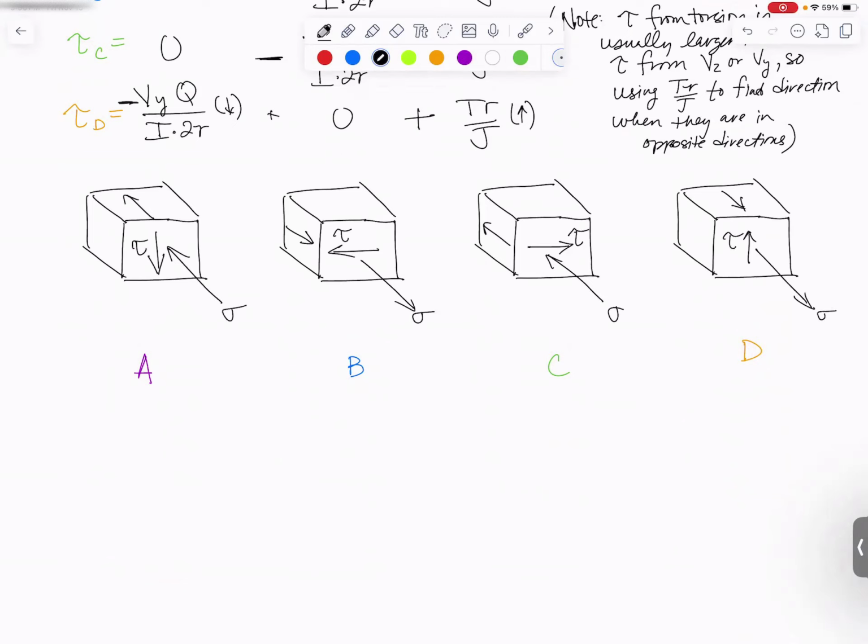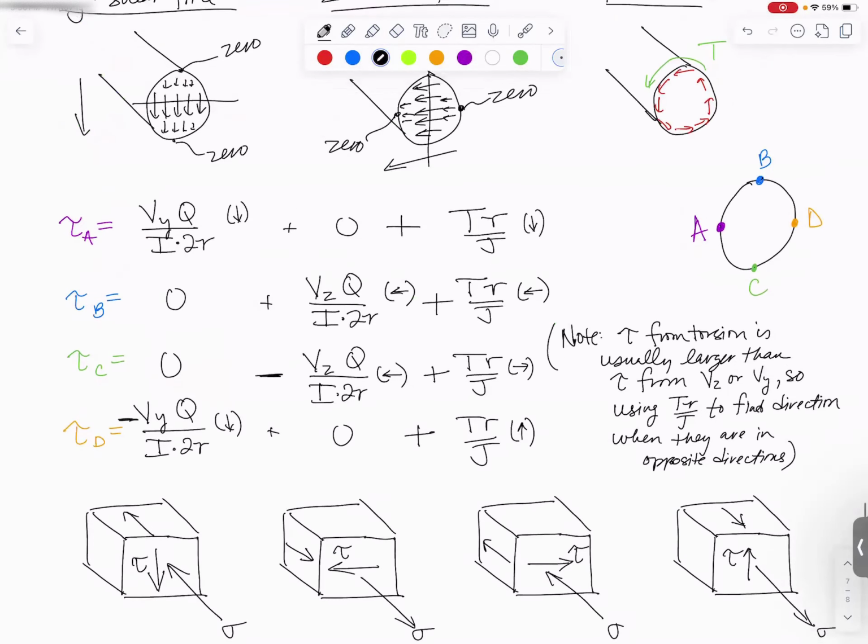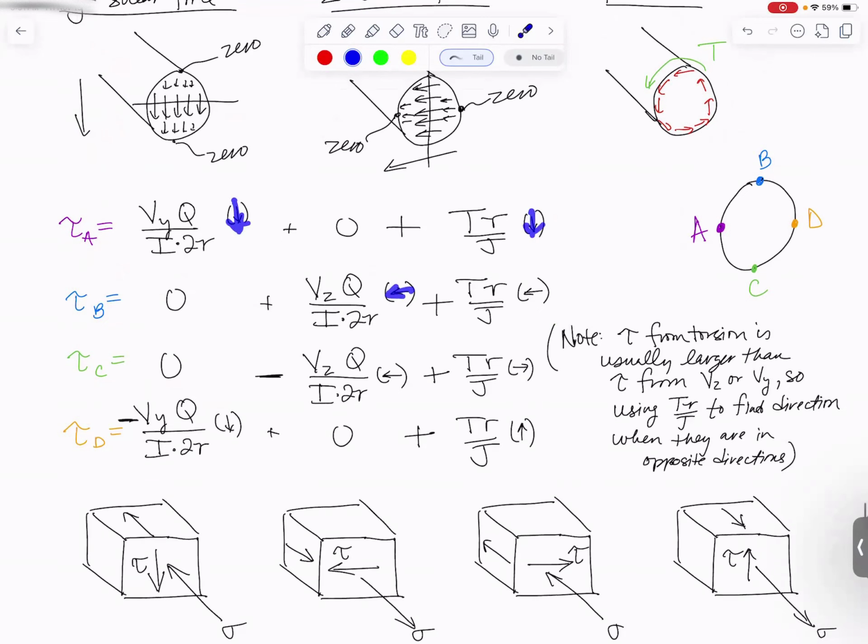There's a little bit of variation in which stresses show up on which face, but this is a pretty typical pattern that you rarely would end up with a stress at a point that goes up and down and another one that goes side to side. They're usually both up and down or both side to side. They might add, they might subtract. And you will usually have some of your stress components that are zero at any given point.